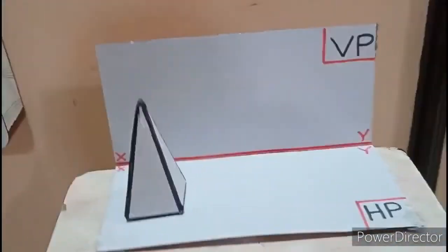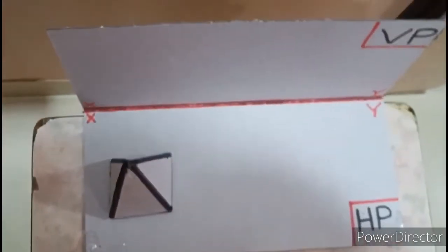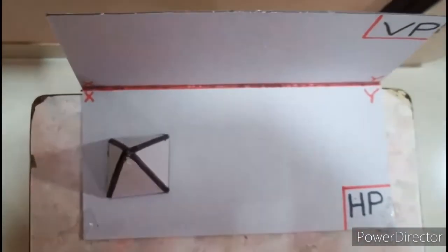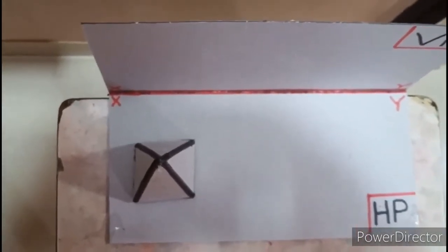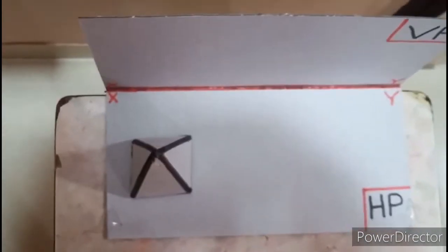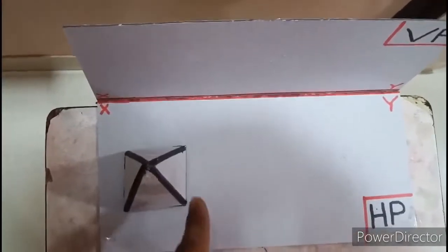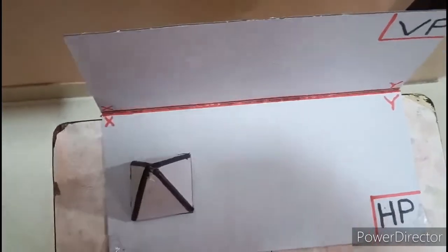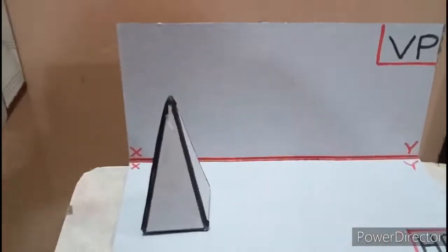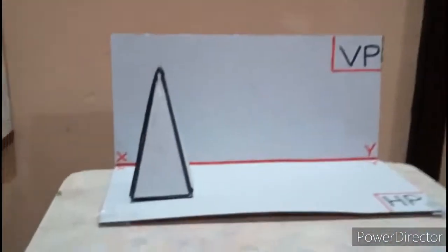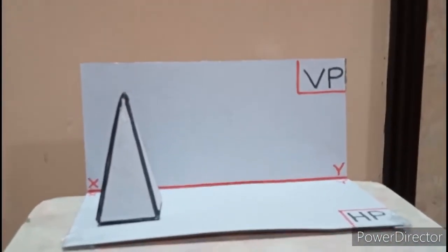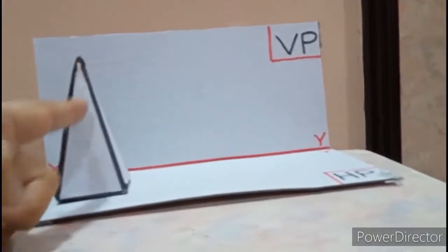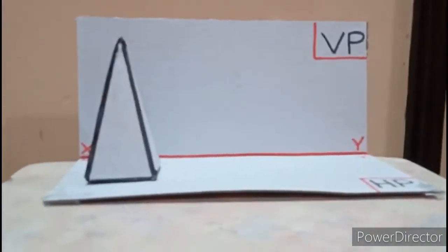So in the first stage, you have started with the top view. You can see the square pyramid rests on HP. In the top view, you can see the square with all the slant edges. And this right side edge is A and B, so this is the resting base edge. And in the front view, you can see only one triangle. The front view is drawn on VP, that is very clear. And because there is no slant edge in the center, you can draw the axis over here.